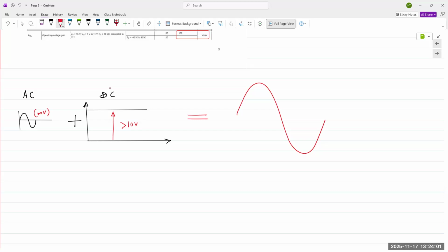There's a preamplifier circuit in there that would amplify the current a little bit, so it makes it a little bit stronger, modulates it, transmits it wirelessly, goes into our amplifier system, and the amplifier system takes that electrical signal, amplifies it again, so now imparting more voltage or more current to it. And the power to do that comes from either the battery that's inside the device, or if it's the computer, then it comes from the DC power source that's inside the computer. Okay, so any amplifier, the energy to work comes from the DC source.